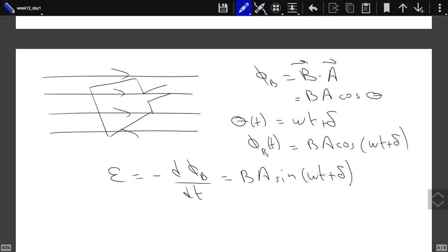Because what happens in an electric motor is this. This is your dipole. You send some current, and let's say you are sending current through this end, and that comes from this end. If the current is running in this direction, what is the direction of the magnetic dipole moment? This way, something like this. Let's say the magnetic field is in this direction. If this is the magnetic dipole moment, it will feel a torque in this direction.